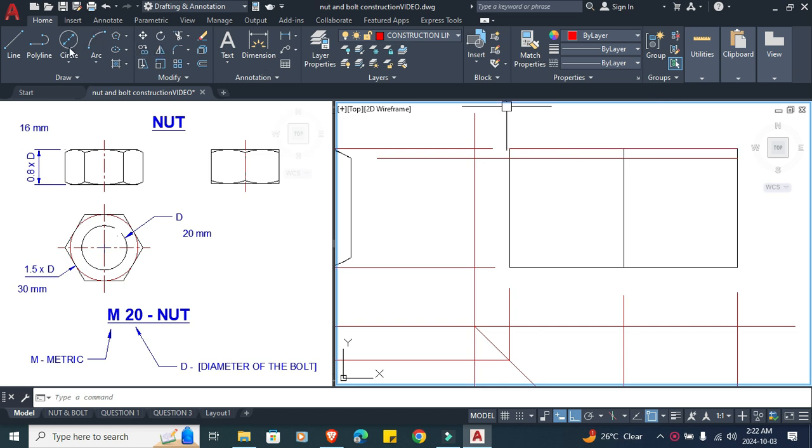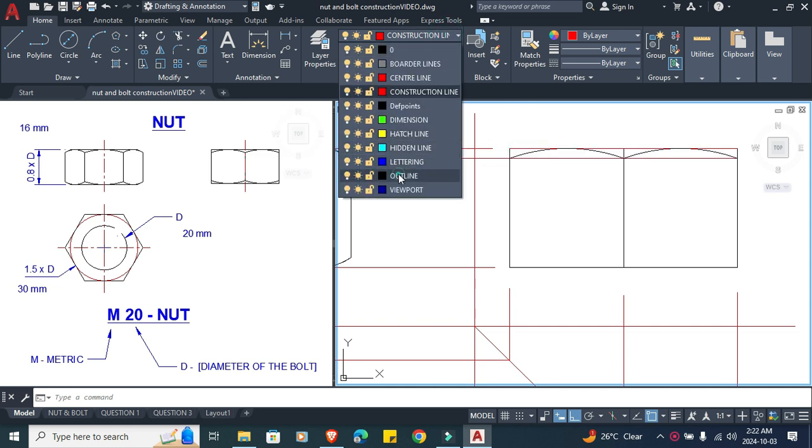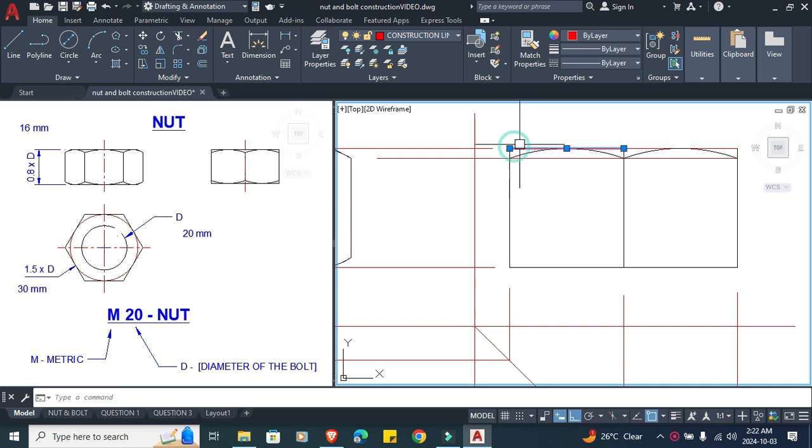Now using your arc command again, at this point 1, 2, 3. Again repeating 1, 2, 3. These curves should be in your outline layer. These lines you had drawn before, you can remove them. This one can be shortened, and you need to trim off this piece here.